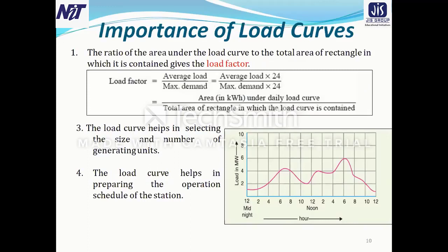So here I am going to discuss the importance of the load curve. The ratio of the area under the load curve to the total area of the rectangle in which it is contained gives the load factor.